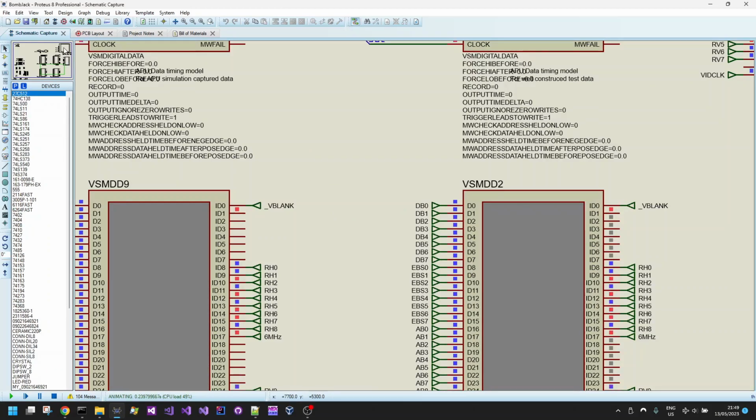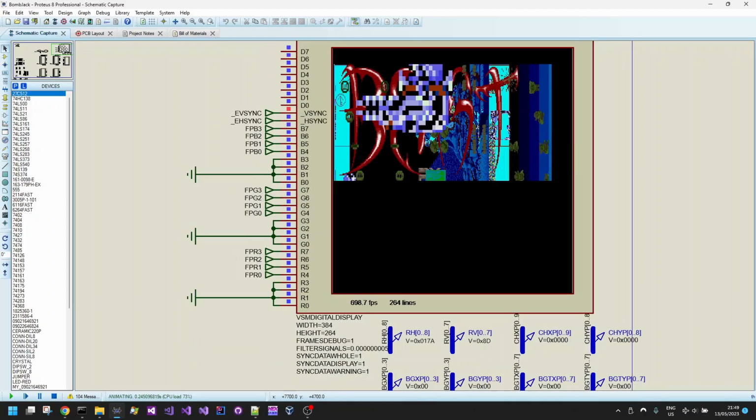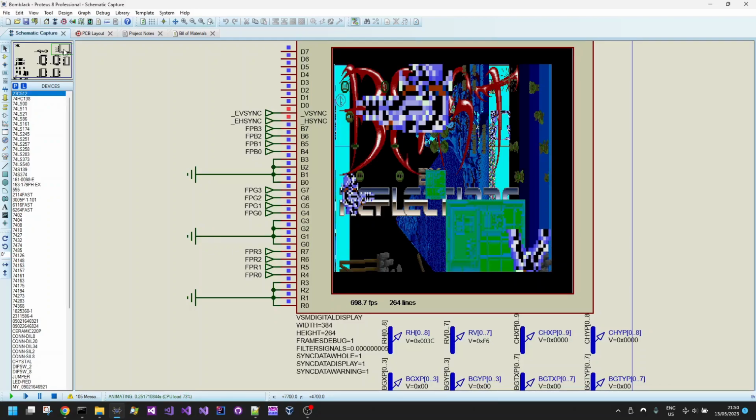This is so I can test the video hardware with different write speeds. Because the video hardware can use the output from the APU, which is very fast, or it can use the output direct from the Commodore 64, which is actually a lot slower than the APU. If I remember rightly, because the Commodore 64 is only 1 megahertz and the APU is up to about 12 megahertz, the APU can output memory on every other cycle, effectively.